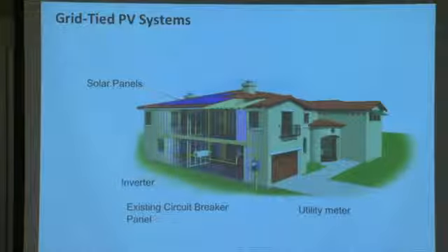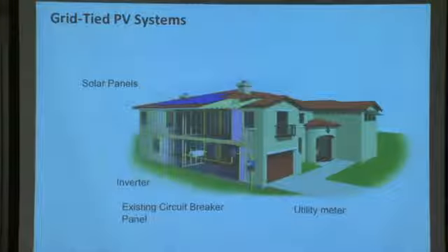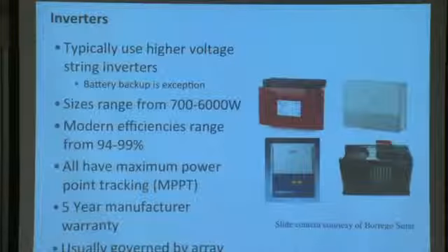Why is that important? The utility companies know that on my house in Cambridge, there is a solar array, and that array is connected to the grid. Let's imagine a tree falls in the power lines during the next storm, and the utility crew has to go out there to repair it during the day. They know that although the rest of the grid is down, there's that one little power center on my house that's injecting power into the grid. And so they'll come along to my house, disconnect the solar panels from the grid. They'll go to my neighbors, disconnect theirs as well, go to the person across the street who also has solar panels, disconnect them, then go to work on the utility line. So that's why the external circuit breaker is very important.